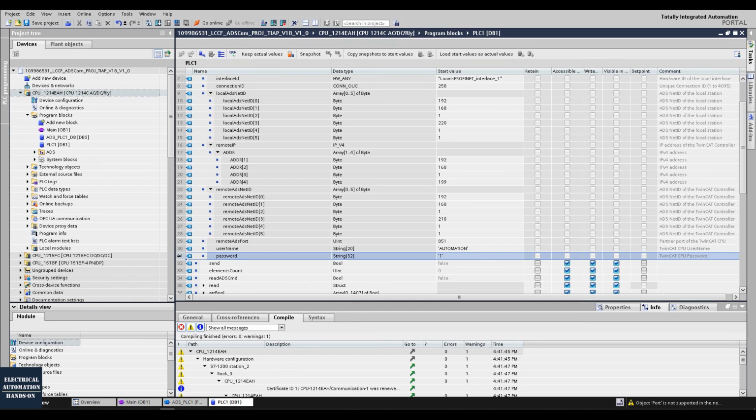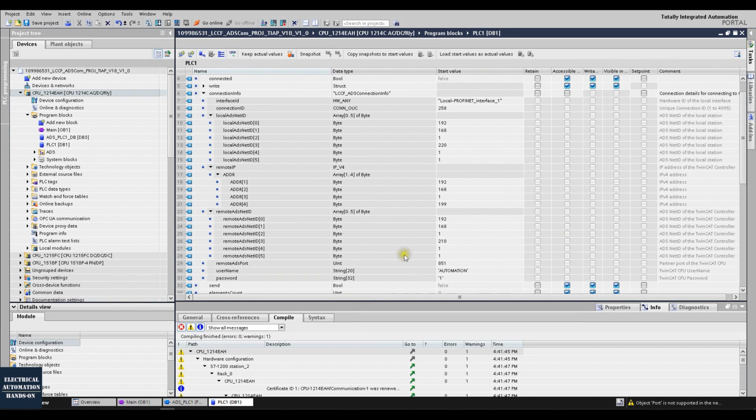And we can immediately see how we can troubleshoot this case. If you cannot set up this ADS successfully, in most cases it comes from the username and password not being set up correctly. Again, I will set up this password as a wrong password, and let's troubleshoot that. Okay, those are the important connection parameters.